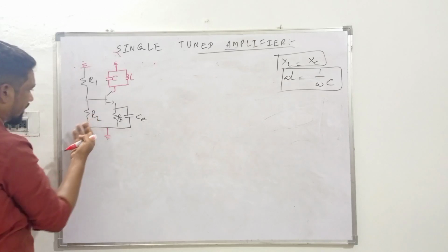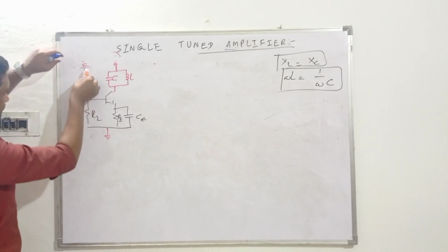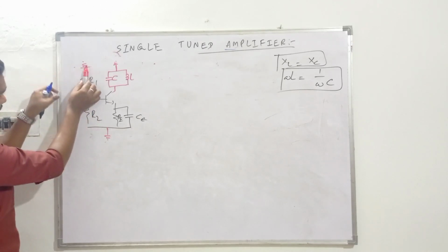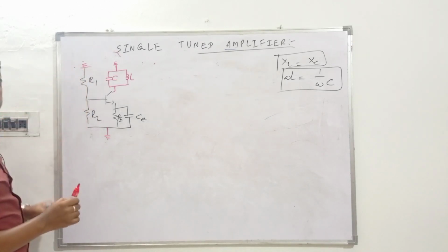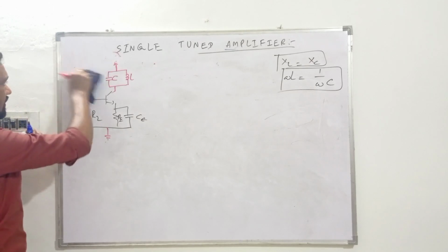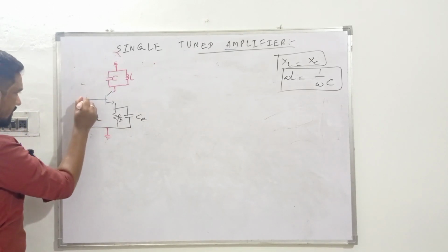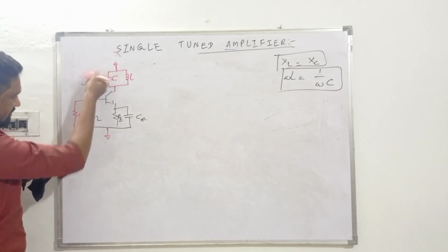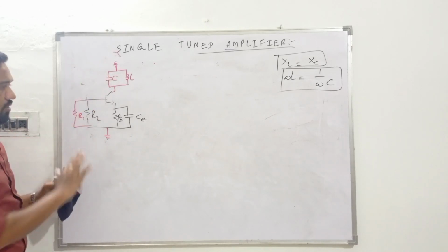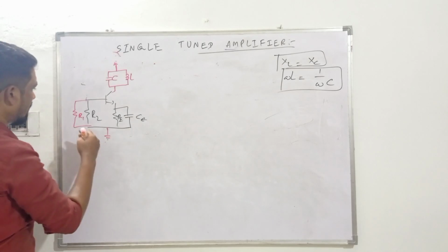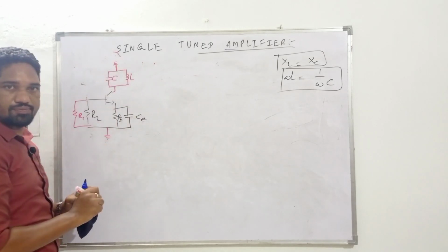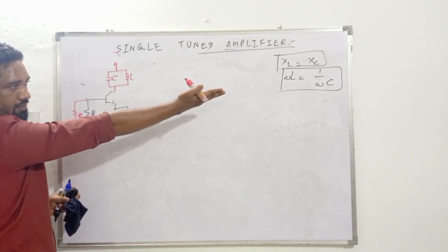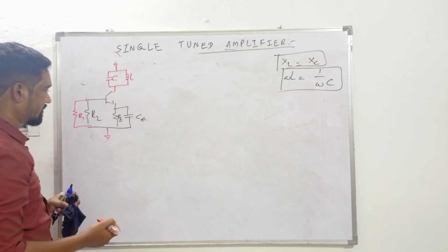With this arrangement, see, here is the ground, and it comes down. R1 comes down like that, so R1, grounded on the other side, comes in shunt with R2. So here the ground comes down. This is the modification in the circuit which we see when it comes to AC analysis. It's all about AC analysis, not the DC. We are working on frequency components, so it's a frequency analysis, okay?